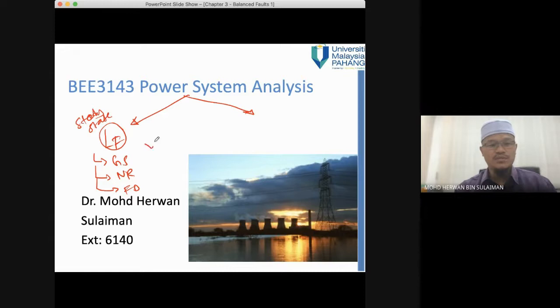We want to find the voltage, the angle at each bus, as well as the P and Q, as well as the power transfer from the sending end bus to the receiving end bus, and we want to find the loss. Okay, so Sij, Sji, then you can find the P loss or Q loss. And then we obtain the complete load flow solution.